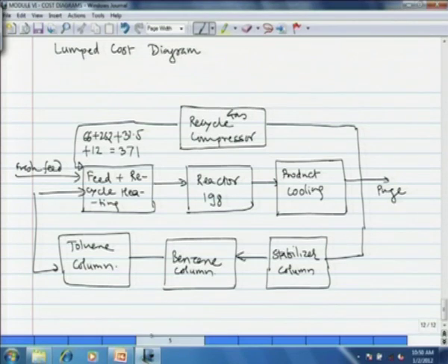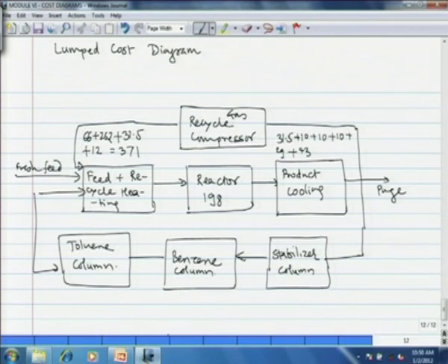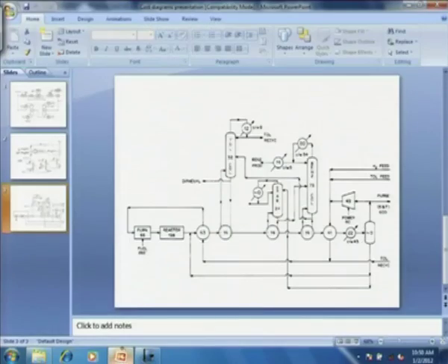So 31.5 is the cost of toluene recycle heat, then $10,000 cost for the 3 columns' reboiler, plus $29,000 cost for fresh feed heating, and finally $43,000 for the cooling condenser, plus $22,000 for the condenser cost. So $43,000 is the cost of cooling water required for the condenser, $22,000 is the annualized capital cost of the condenser. So together these make out $155,000. Okay. Now let us see the gas compressor.